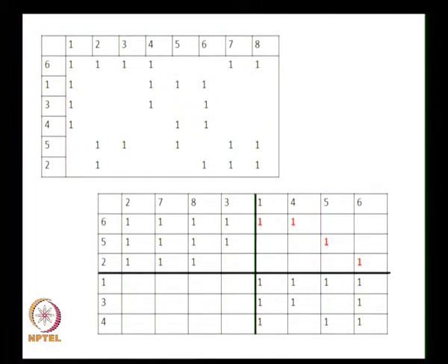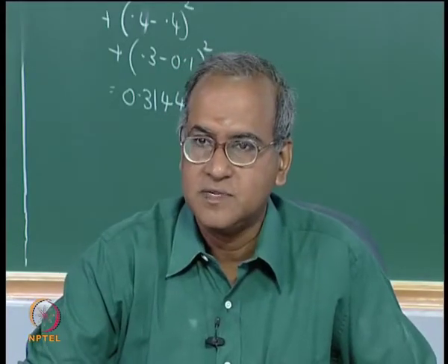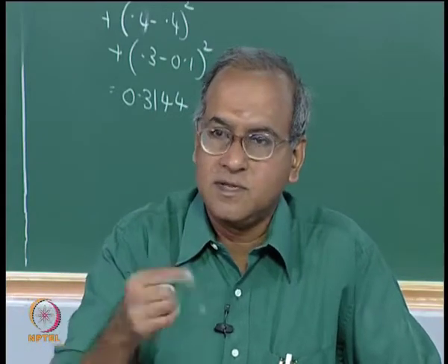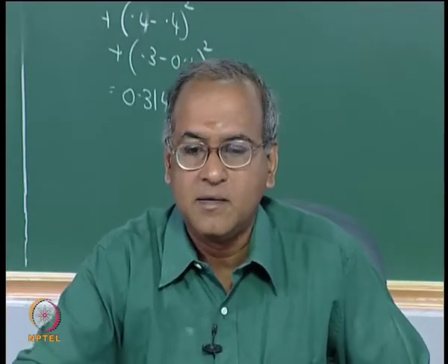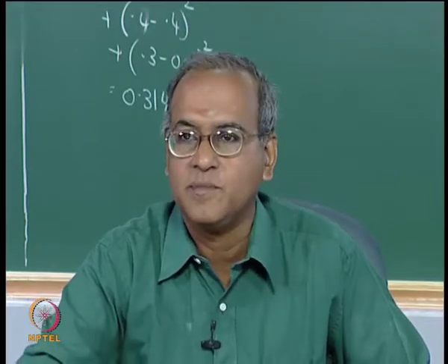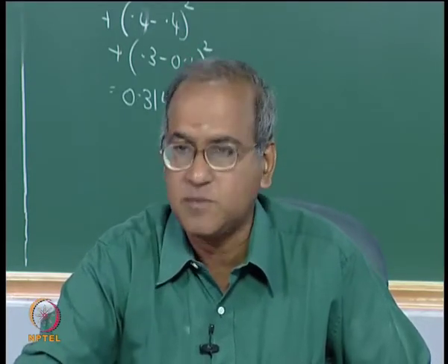Second aspect is called alternate process plan. For example, if I take P5 and if P5 is right now doing M5, M1 and M4, if there is an alternate process plan by which it can do in M5, M6 and M2, if it could, then we could choose the other process plan and P5 will come into this group and it will visit M6, M5, M2.